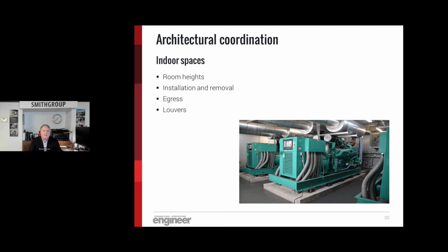So as Dan mentioned, one of the options you have with placing the generators is inside or outside. We have to work with the architects. It's a complicated relationship. One of the things you have to look at, and I know that it can be challenging to determine the size of the generator early in the project, particularly when you're going beyond emergency systems, which are easy to estimate for a building, when you start talking about standby and or owner wish list optional loads.